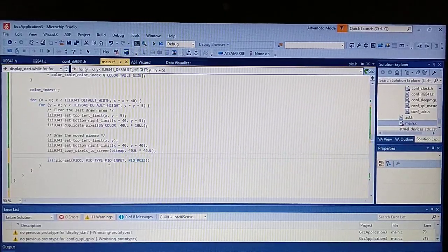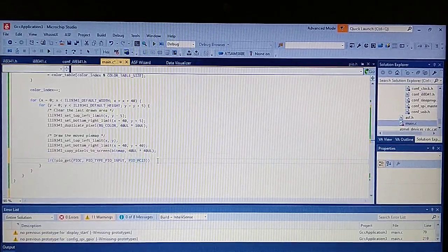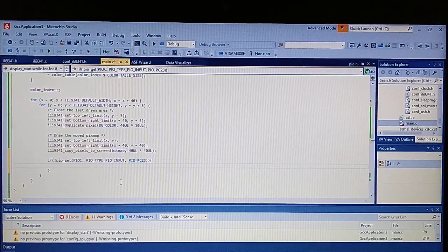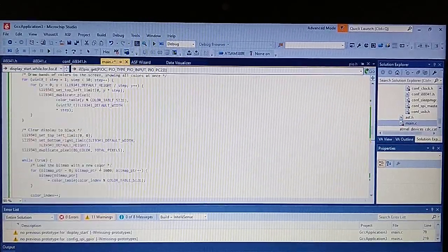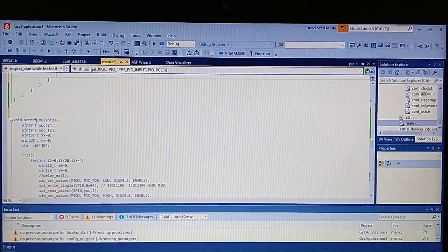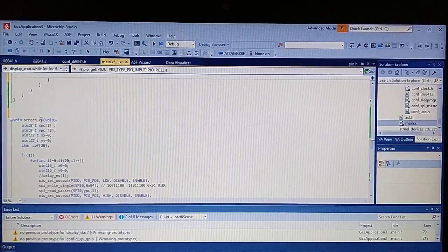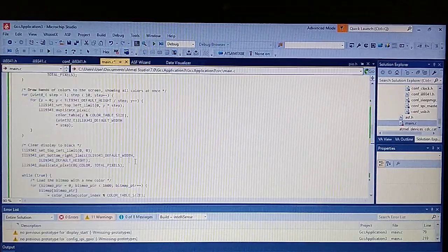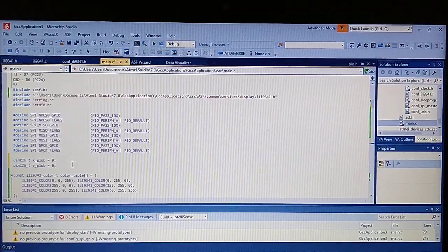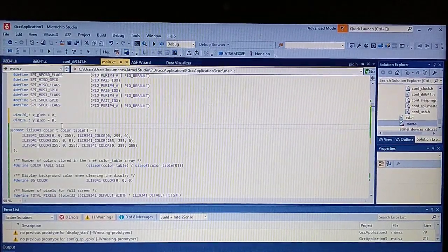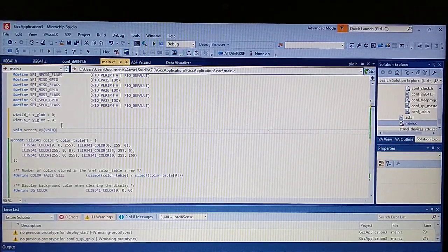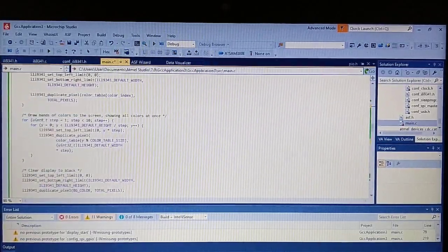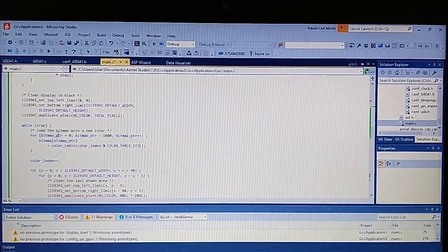So whenever this pin is low, then we will trigger our function to read the coordinates. And also we need to make a prototype for this function to get access to it, so we don't get any errors, because it's lower in the code than the function we will use it in.